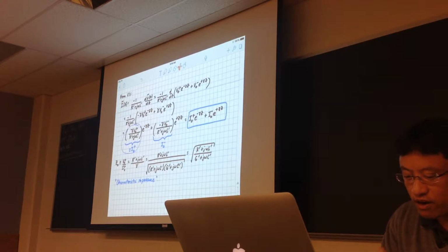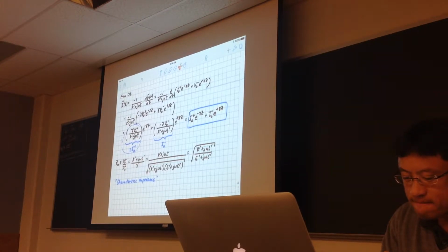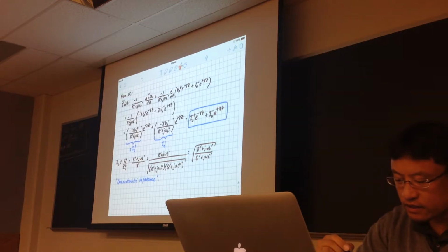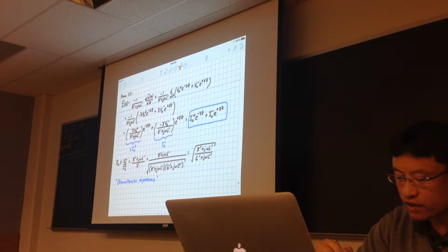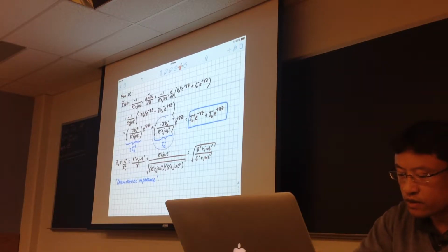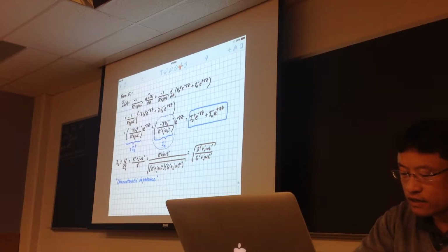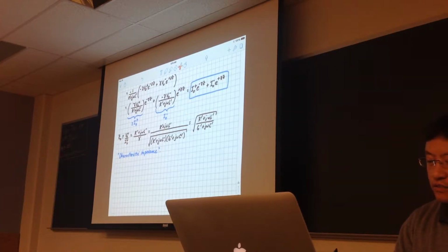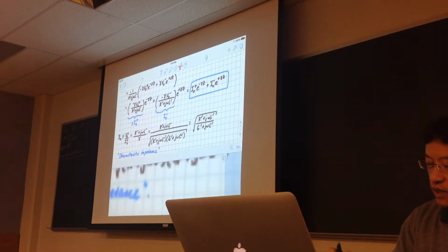And so if you take that ratio V0 plus to I0 plus, you get R prime plus j omega L prime over gamma. And plugging in for gamma as the square root of R prime plus j omega L prime times G prime plus j omega C prime, and doing the algebra, you get that the characteristic impedance is that. Note that the characteristic impedance is R prime plus j omega L prime over gamma, and that appears here also, R prime plus j omega L prime divided by gamma. So the characteristic impedance is also minus V0 minus over I0 minus.